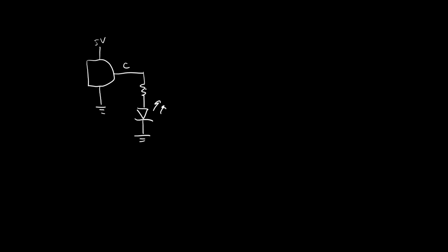And again, we want this LED to turn on when the output is high, and I'm using an AND gate because I only want that to happen if both buttons are pressed. So I could wire buttons to my 2 inputs here, where I am going to have push buttons connected up to 5 volts.